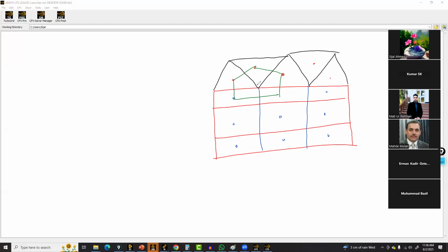Okay, and secondly, CFX does not allow you to use the dynamic meshing. Why? Because it has very peculiar element types that are not suitable for dynamic meshing. So dynamic meshing is not allowed in CFX, although you have the option to stretch the elements while keeping the same element shapes. You can stretch them, this line can be elongated here, but that's all. You cannot regenerate and make new elements like you do in the Fluent, because it has very different element shapes that are generated, not the original one that we have provided in the mesh.